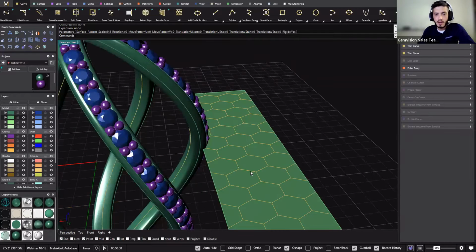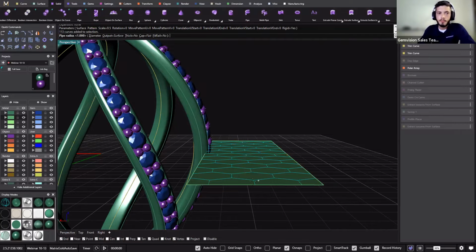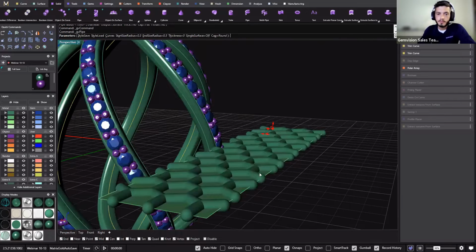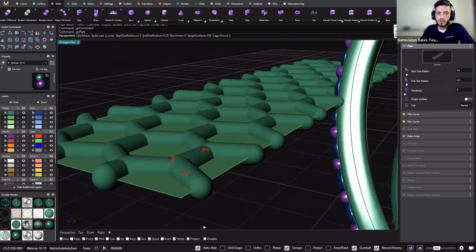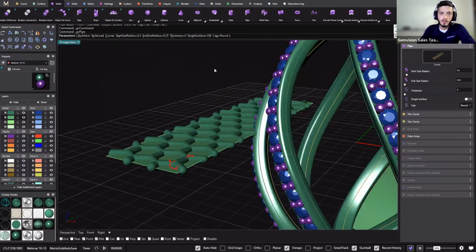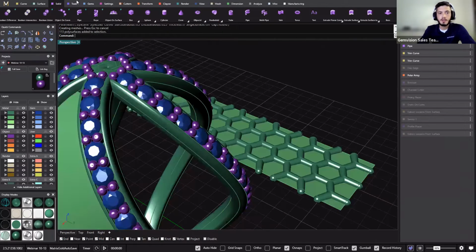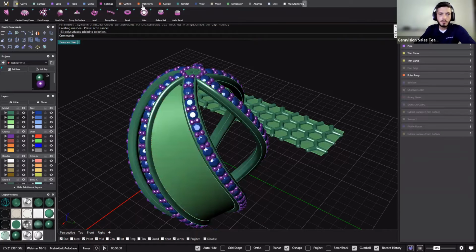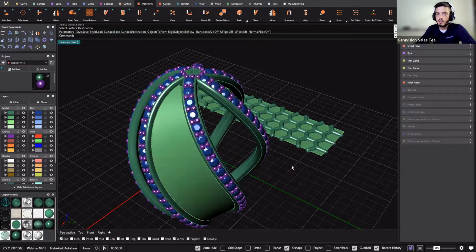Let's bring our curves back. I'll select these and then we can pipe them. Dynamic pipe them rather. And let's go down to 0.25. Enter. And hide this. So now let's see if we can smart flow or flow on surface. Not auto base, smart flow, base, destination, enter.